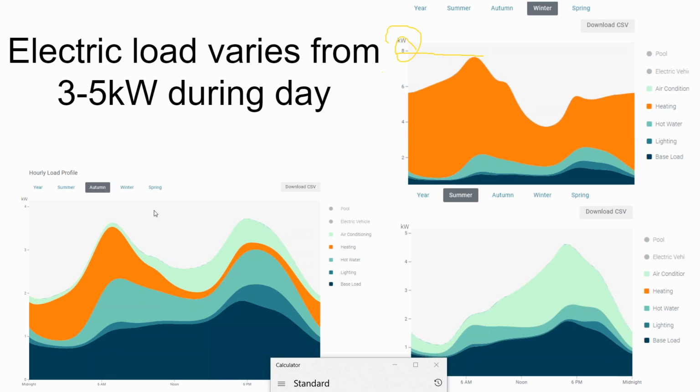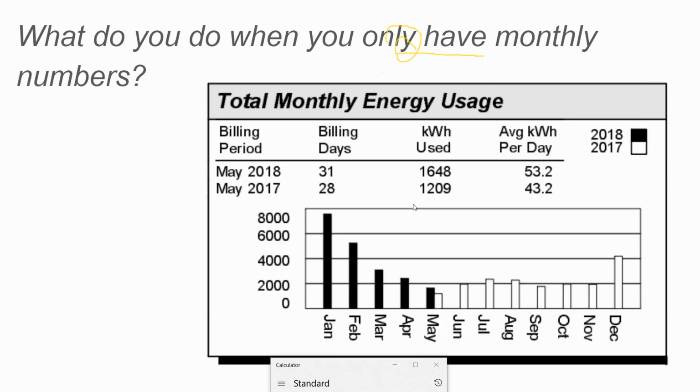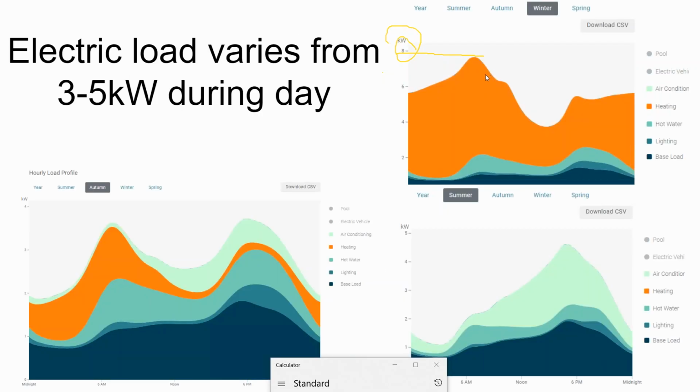This particular customer's bill shows a maximum draw of 8 kilowatts, and then kind of a sustained draw. Maybe we look at a 30-minute window or maybe a 1-hour window at around 7 kilowatts, and they're mostly below that. So I say, okay, I need an inverter that is capable of delivering 8 kilowatts of power to this client.